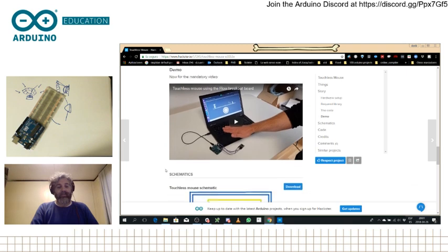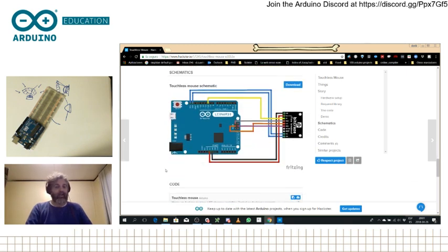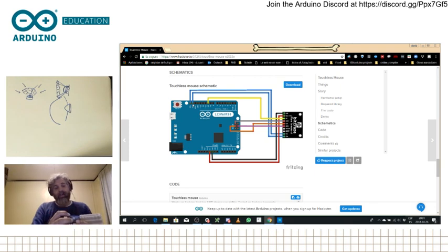And so first thing is to mount it, and this is for the Arduino Leonardo, where you have the pinout. And as you see here, they take the I2C from the last pins on the board, which my board has up here, and then they take the SPI from the connector here. The thing with Arduino Uno is that connector there is also replicated on the pins 9, 10, 11. So I could do that as well. But I think I brought a whole lot of cables. Just to be safe, I can do the exact same connection as you see in this drawing.